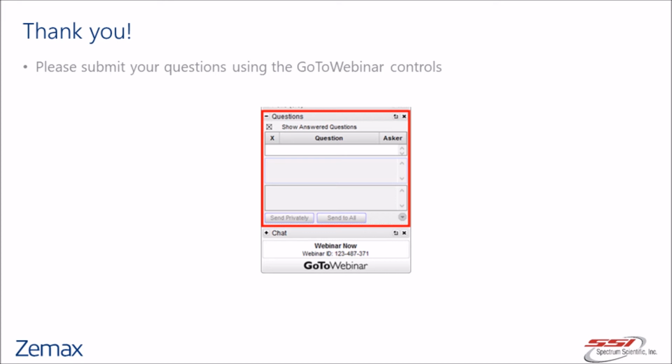The first question is, isn't finding the best fit sphere non-trivial for a freeform optic since we are non-rotationally symmetric? Yeah, that's right. It is non-trivial. It's useful to find a best fit sphere though, because it ties into your interferometric testing. Your interferometric testing will typically remove the best fit sphere, and so what you see in the interferogram is really the departure from the sphere. In order to set up your interferometric test correctly, you do need to make some assumption about the best fit sphere, and it's the departure from the sphere that you care about.